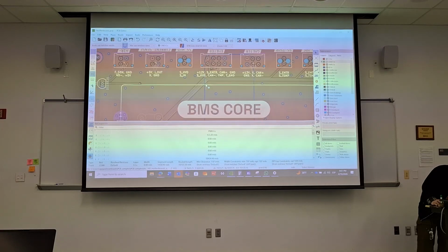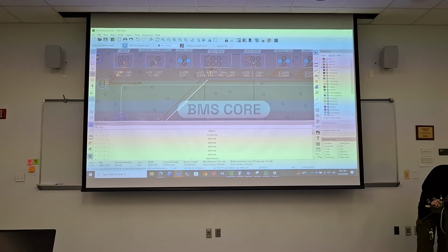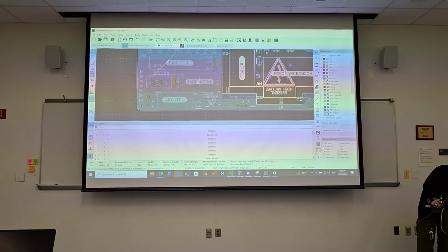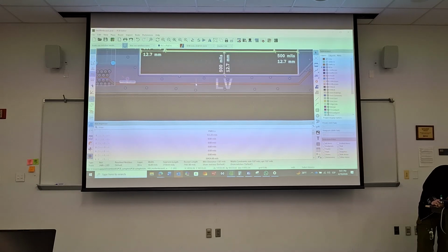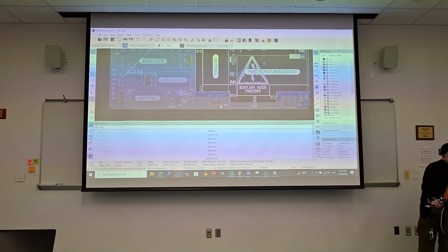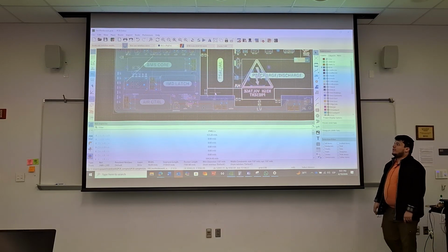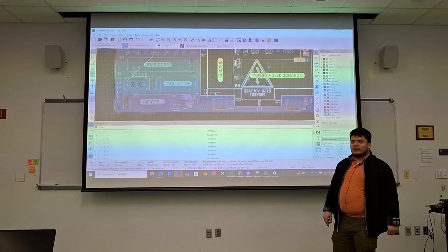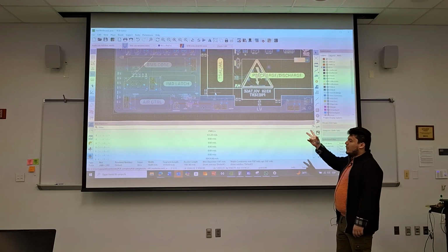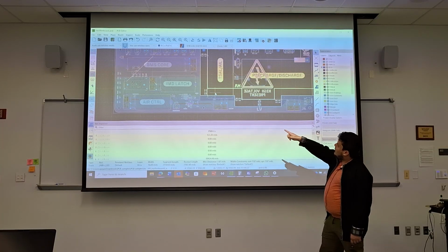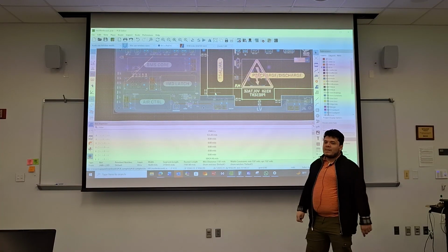But this, let me see. This is 7 inches. If you look at your transmission line model, that is huge. Then we also have these signals that are coming all the way from the edge of the board. So on a board like this, I would really even go higher than a 4-layer board so that you have good shielding within all of those sense lines, because you just have huge inductors. That being 7 inches is crazy.